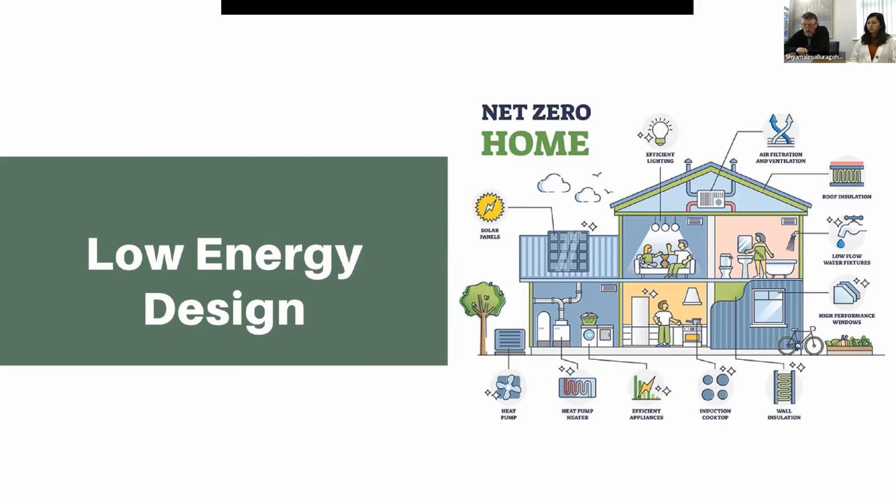And through transmission distribution of that electricity, a lot of electricity is lost, and there's a conversion factor to represent that. And it used to be as high as 2.08. So in other words, for every kilowatt of energy you use in your house, 2.08 kilowatts had to be generated, and the balance was lost.